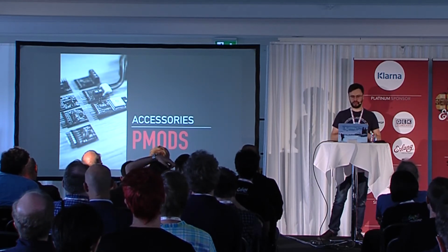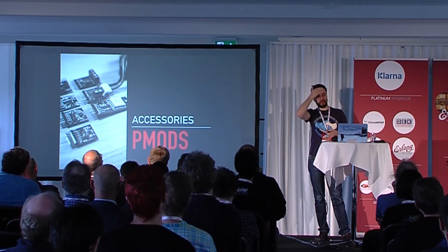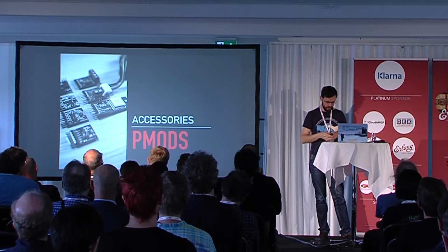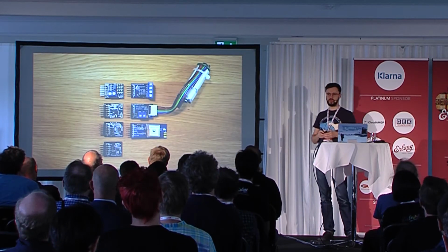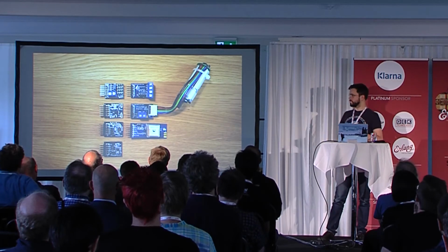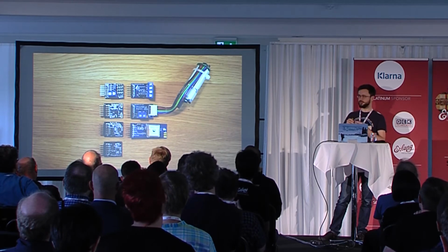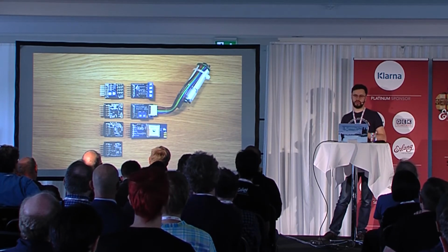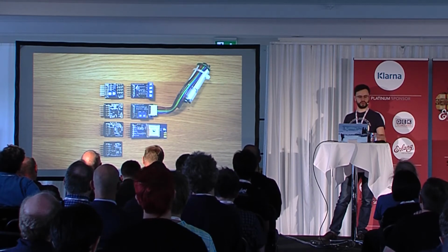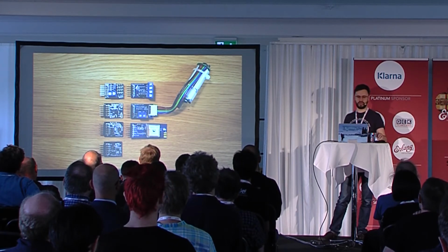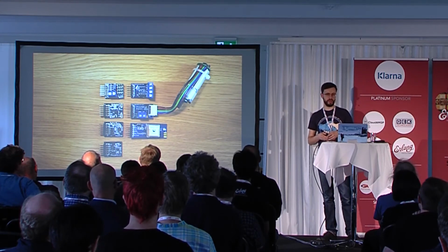So next up, I'll show some examples of what you can connect to this device, and I'm going to focus on something called PMODs. PMODs are a standard by Digilent, and they're small components with 6 or 12 pin ports, and they usually talk one of SPI, UART, or GPIO, which means you can plug them into all of these ports and use them. So I'll just give some examples of components that you can buy.